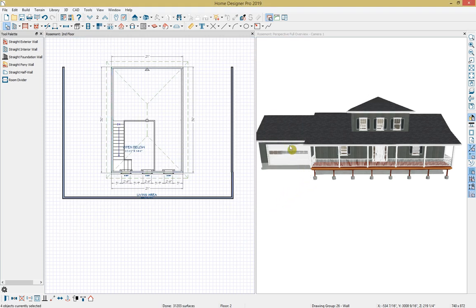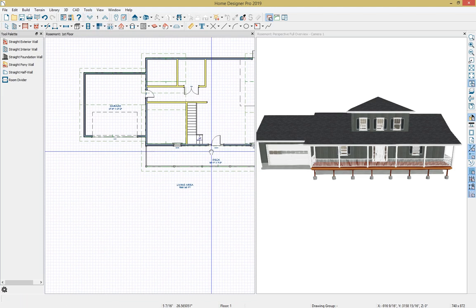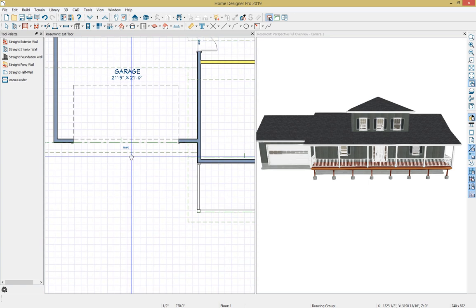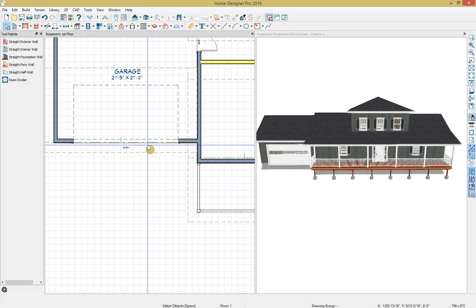And now it's time to create those gable walls with the full returns over my doors. So I'll go back down to the first floor, and I'll start with the garage space. Now, so far we've been using the automatic tools in Home Designer. I will show you how you can create this using the automatic tools, and then with Home Designer Professional, you gain the ability to create manual adjustments to your roof system, so you have more roof control. So I'll show you that variation as well. But let's go ahead and start with the automatic tools.